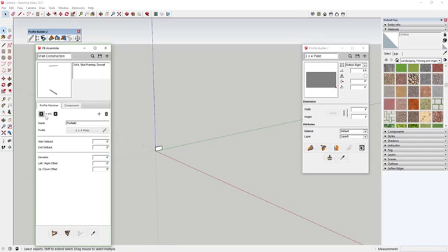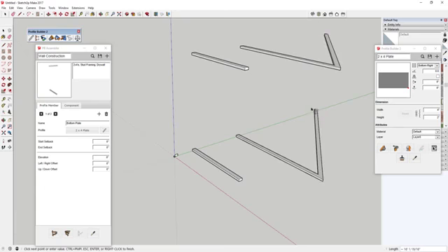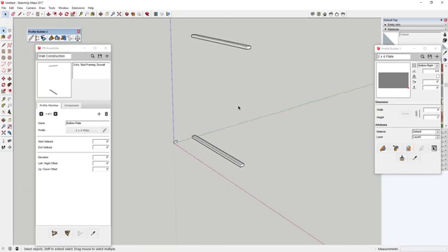So now it knows that you have one 2x4 plate at the bottom here. We could probably just name this bottom plate, and then the second one we could call top plate. So it knows that you have two profiles in here for your bottom and your top plate. Now if you were to come in here and draw this, you can see that it draws both your base plate and your top plate, just like this. Now you've got an assembly that follows wherever you click, just like that. So that's where we want to start.